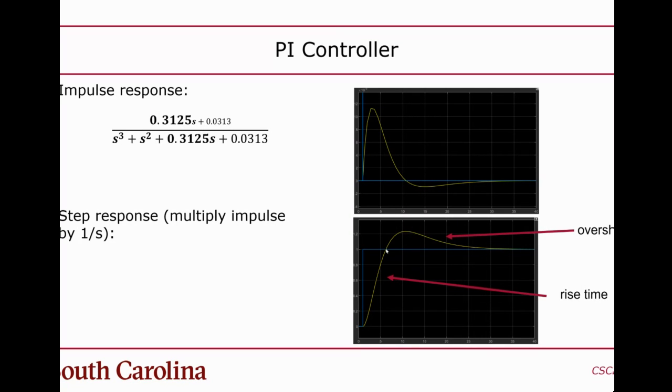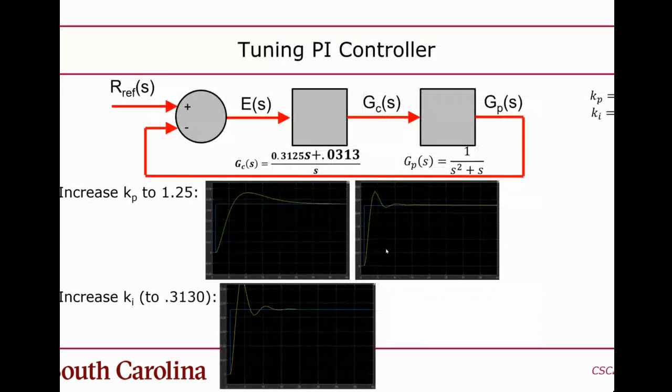And then the problem is that it's going to drive past 1 meter, up to just over 1.2 meters, and then it's going to drive back to 1 meter very slowly, and that's the overshoot. And that kind of stinks. It's not a great robot controller, although technically it's working. It's just not working really well. So you can tune this.